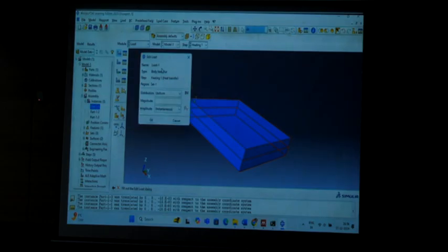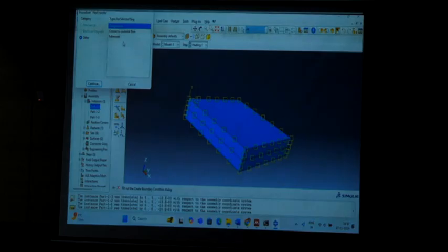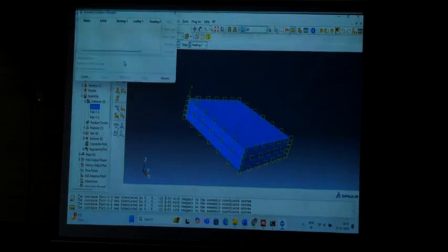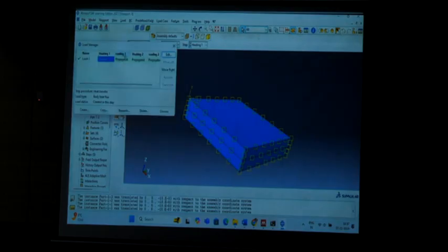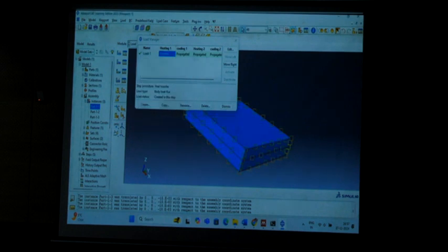So that load will be convection. The heat will be distributed all around the surfaces. So what is the magnitude? You can give it some value, some 20 or 1 power e power 5, anything. Click OK. So heat was distributed, we have given the loading conditions of heat in the form of convection on all the surfaces. Here you are going to create a boundary condition. Okay, not required. Go to this option, edit. We have given the flux.